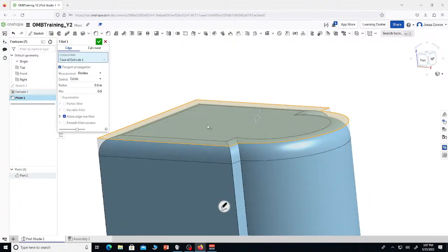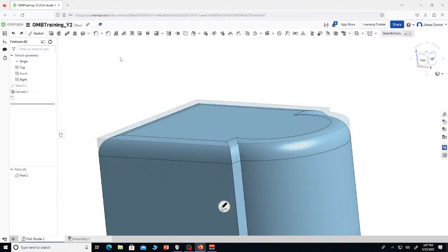You should always smooth your parts out when you're cutting them out on plexiglass. This year, if you were to do your intake and you were to have a corner, it would definitely pop a cube sometime during the year, so you'd want to smooth that out. And you can have the CNC machine smooth it out for you while it's cutting the part, instead of having to get a file and just file it out for forever. You can fillet it before you cut out the part or order it.